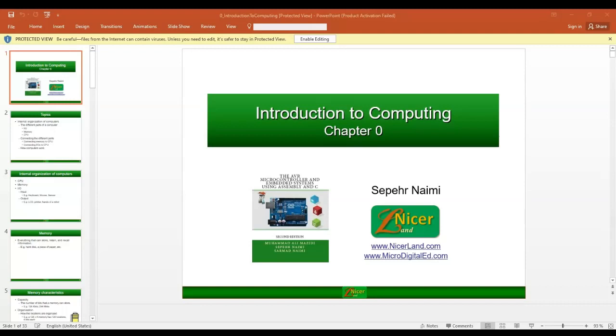To write on a memory, we give the address of the place where we would like to write, and then we have chip select. We give an active low signal to the chip select pin, and from the data pins we give the data which we want to store at this address, and then we enable the write enable pin by giving an active low signal to it.